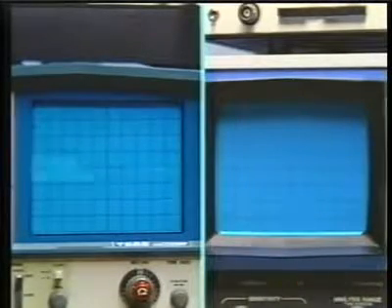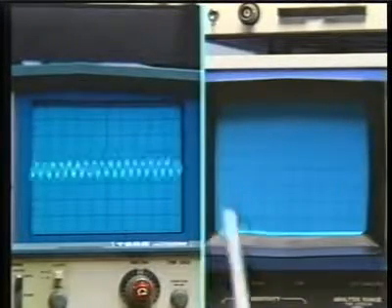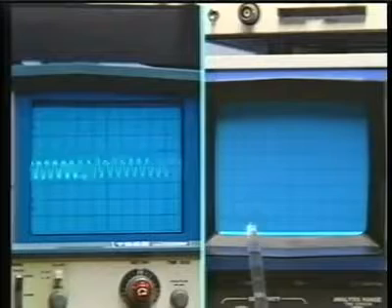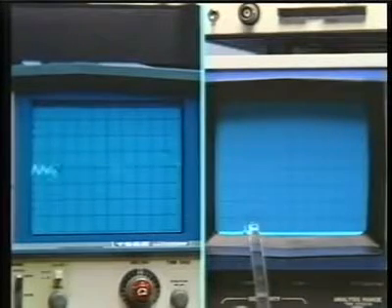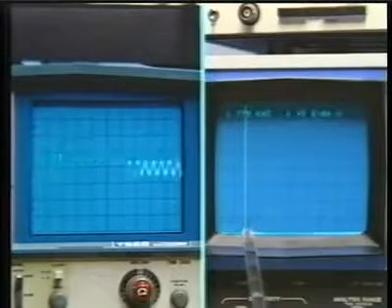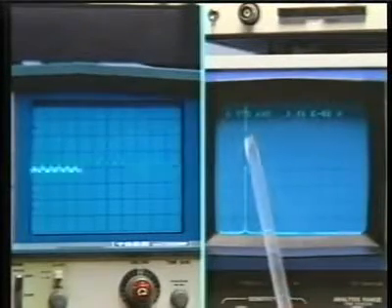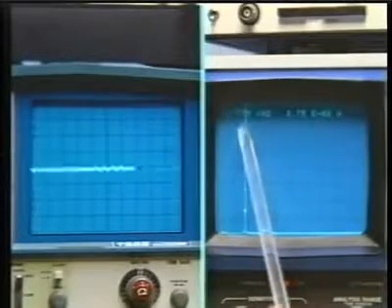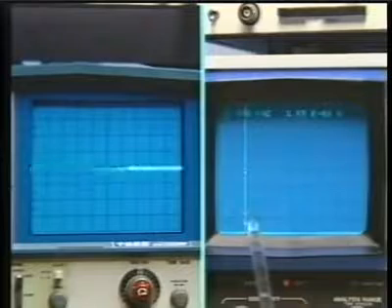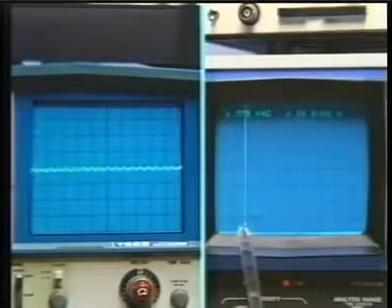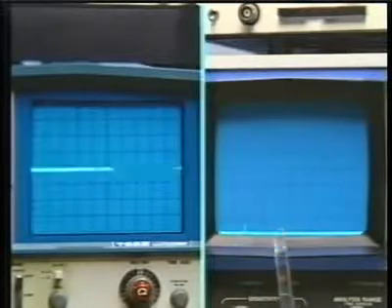So here is the spectrum. Over here we have the time waveform. And here is then the first spectral line, and we can see where that is by setting up the cursor, and magically, once again, I have the cursor positioned in just the right spot. The first spectral line is at 1.775 kilohertz. And so this is the spectrum then of the original glockenspiel note.